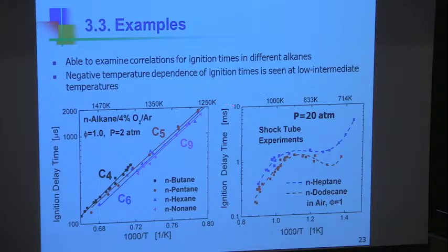What if you go lower? If you go lower, you have this interesting observation that the ignition delay time starts becoming independent of temperature, and then it goes up again. So that's telling the theorists that the chemical kinetics mechanism is different here than it is in this region. We call this the NTC, negative temperature coefficient regime. Negative temperature coefficient means that for some reason, as you go lower in temperature, the ignition delay time actually gets shorter, which is counterintuitive. But that's because of the details of the chemistry.